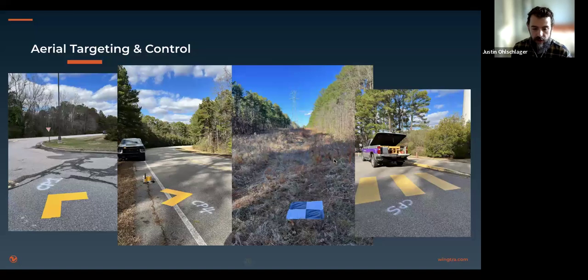And then, doing the strip alignment also gives us visually a really good sense of how the lines are lining up with each other. So if for some reason during acquisition something goes haywire with the IMU, or it doesn't connect with the base station, we can easily see some of those larger scale issues pop out at us. So more of a QA/QC kind of situation for us here at McKinnon.